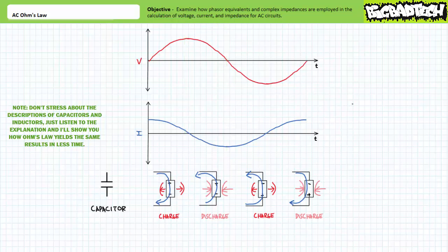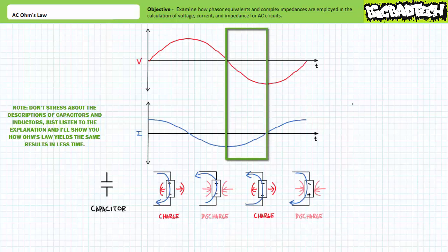When completely discharged in one direction, the charge process begins anew, only in the opposite direction. When uncharged, i.e. has no differential across it, current rushes in and is respectively large in magnitude. During the charge process, an increasing voltage differential develops across the capacitor and current subsides. When charged, i.e. has a large differential across it, current stops.